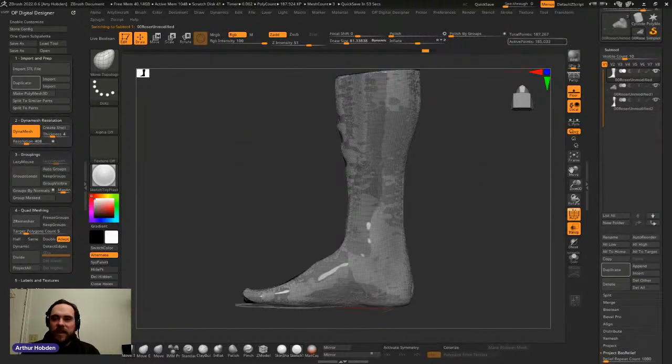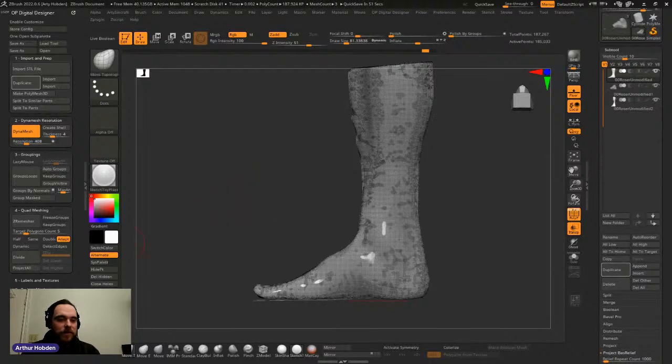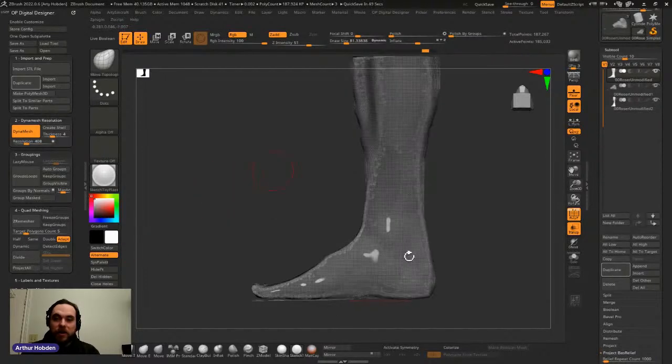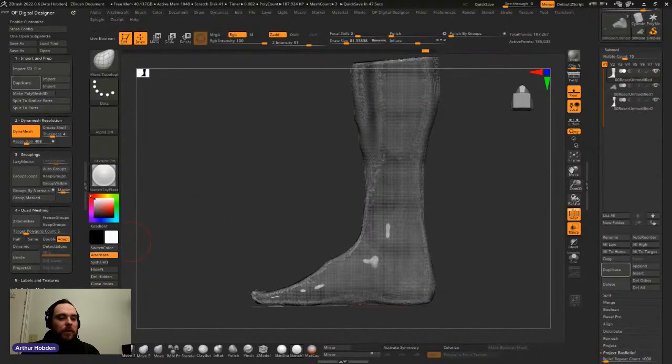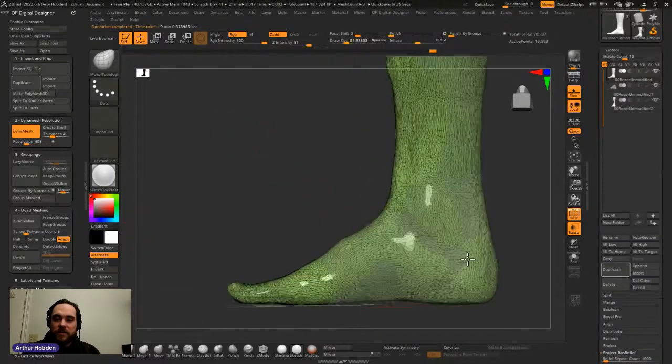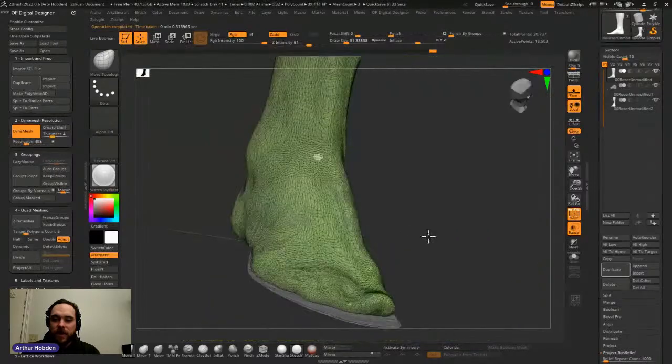And so this at 185,000 points is very unfriendly for CAD. Any CAD package you try to bring that into, it will cry. So we are going to quickly do a reduce function. We're going to process this scan and reduce it to, I would say, about 18,000 points. So 10% of its original size. So if I decimate this, bam, nice and friendly mesh for CAD.